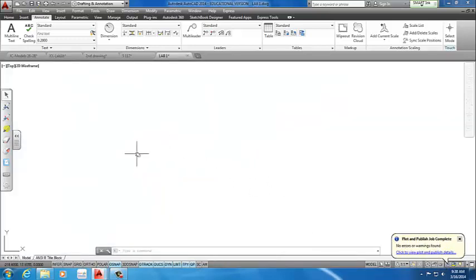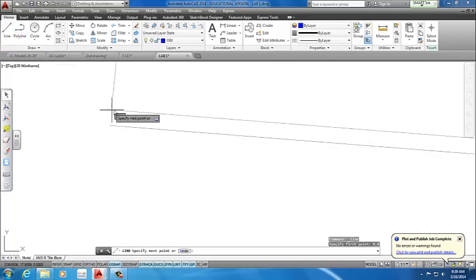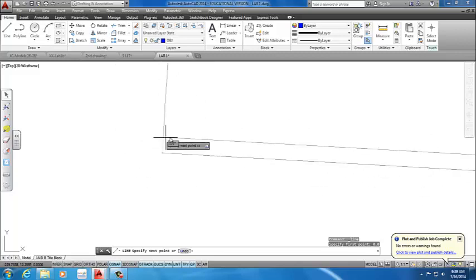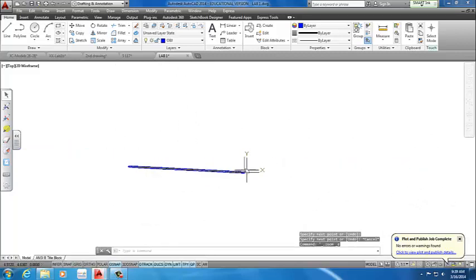So basically what we want to do is create a circle, but before we do that, I want to make sure that I create that circle at the 0, 0 coordinate system. To do that, sometimes the easiest way would be to go to the line command, type in 0, 0, because that's where my line starts, and I click anywhere on the screen. That gives me a line from 0, 0 to whatever point I clicked on the screen. Now I have the center of my origin, which is 0, 0, where I can start drawing my circle.